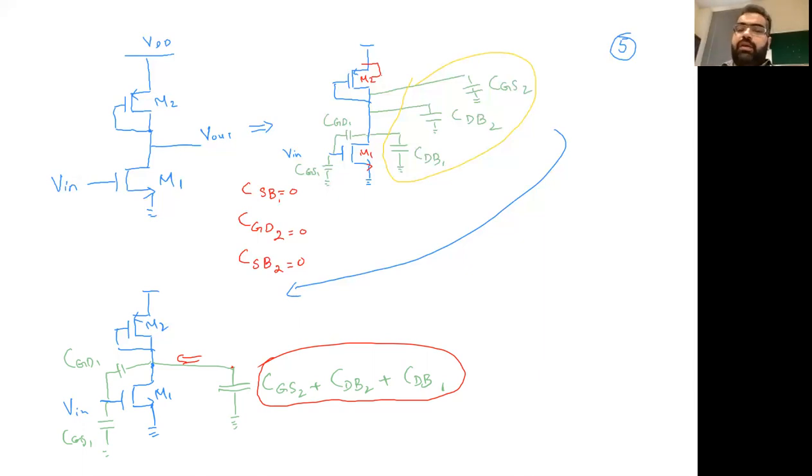If any capacitance is between two nodes, we can use Miller capacitance to separate it into two capacitances between a node and ground, and then again find an impedance and plug it into the Bode plot to find the response accordingly. That's the overall analysis. But let me write the analysis approach which we are going to use in the next lecture to solve some examples.